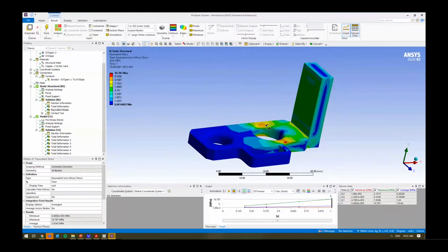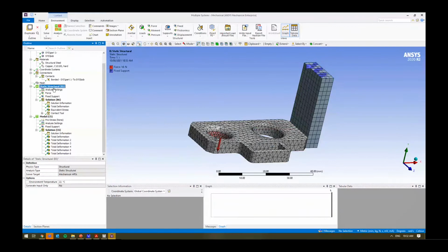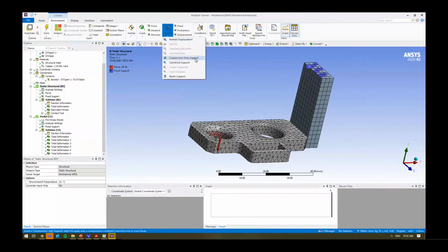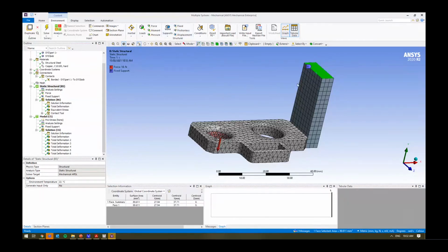That is absolutely correct. This does come down to a bit of your engineering knowledge and your background of understanding what the appropriate boundary conditions are for what you want to do, right? That comes down to your loading conditions, whether it's force, moment, pressure, and also how it's actually supported. There are instances where you might have stress concentrations and you're making some sort of simplifications, so it might be appropriate to ignore the stresses locally around that region.